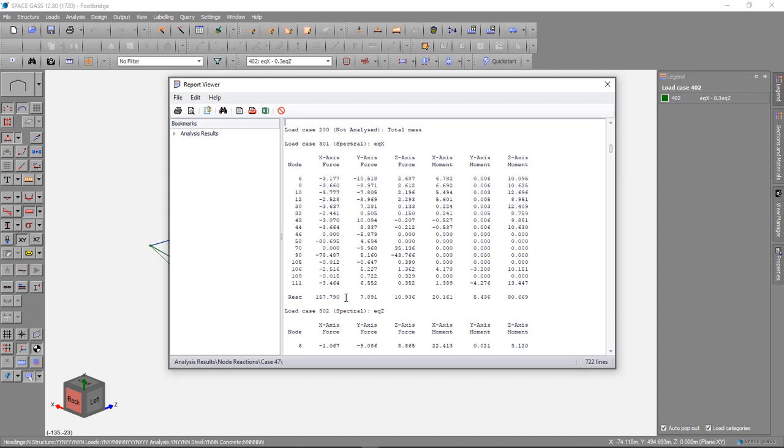However, you need to consider that the analysis looks at the vibration of the structure and identifies the maximum values that result from it. However, the maximums at different points of the structure can occur at different times during the dynamic event. That means that the spectral results don't represent an equilibrium state of the structure, but rather an envelope of the maximums. That's why if you add up these individual reactions, you don't get the same as the total reaction. You also don't get a line that gives you the sum of the loads and the sum of the reactions that should be equal and opposite.